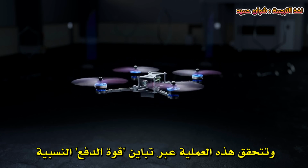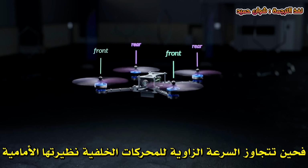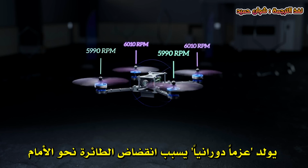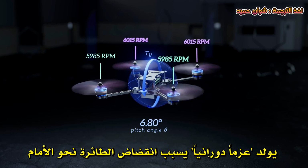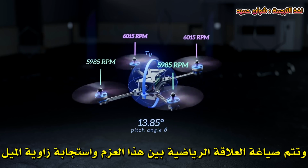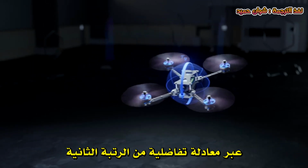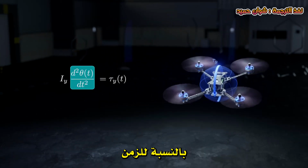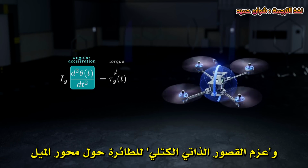This is done by changing the relative thrust of the front and rear motor pairs. If the rear motors spin slightly faster than the front ones, they generate more upward thrust, producing a torque that causes the drone to pitch forwards. The relationship between the torque and the resulting pitch angle is described by a differential equation. The second derivative of the pitch angle with respect to time, which is angular acceleration, depends on the applied torque and the drone's mass moment of inertia about the pitch axis.